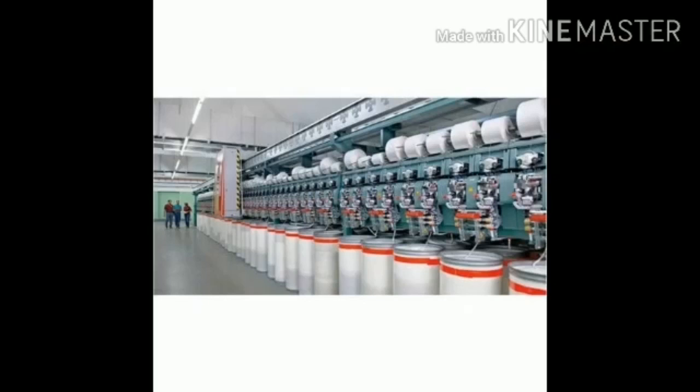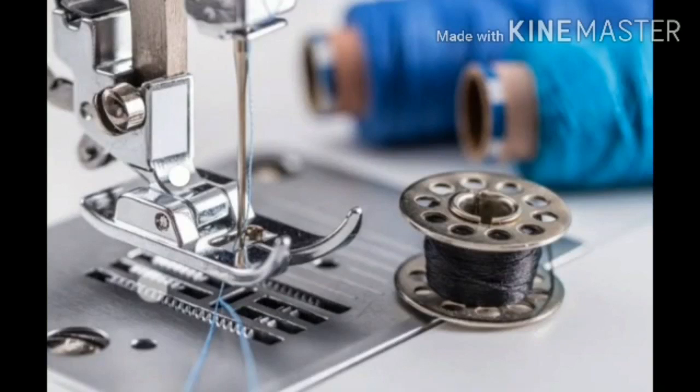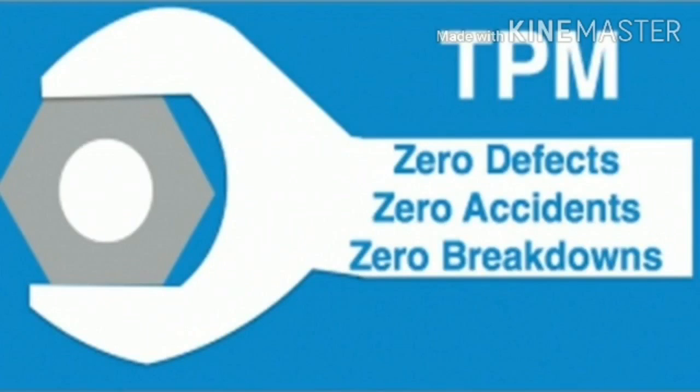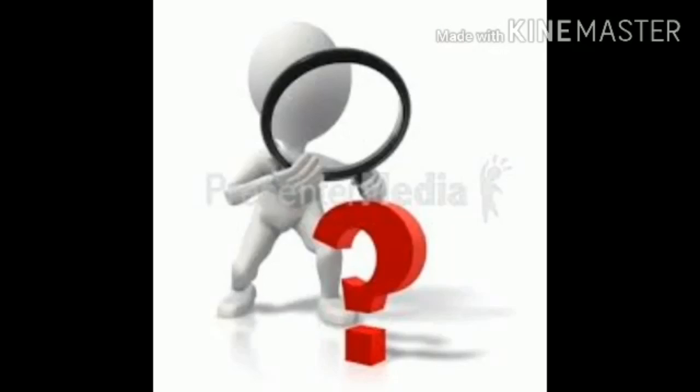In the textile industry, TPM is used in assignments like machine inspection, cleaning, lubrication, needle replacement, and basic machine setting tasks by the machine operators. The key measurement of TPM is machine effectiveness, which includes availability, performance efficiency, and overall equipment effectiveness. TPM is mainly accomplished through 7 pillars which help to ensure zero defects, zero breakdowns, zero waste, and zero accidents with total employee participation.